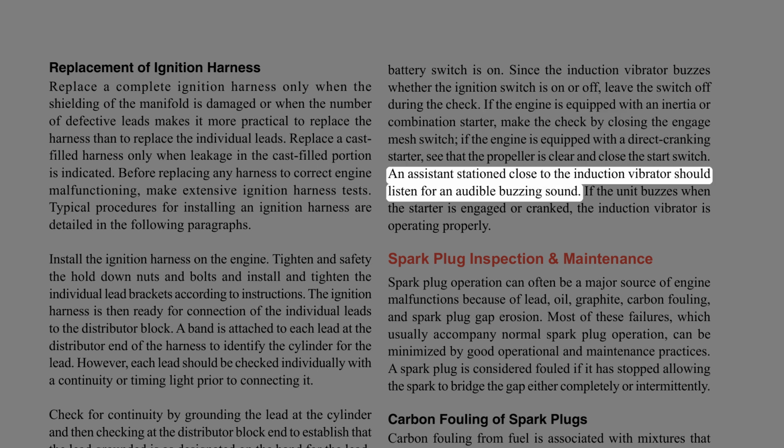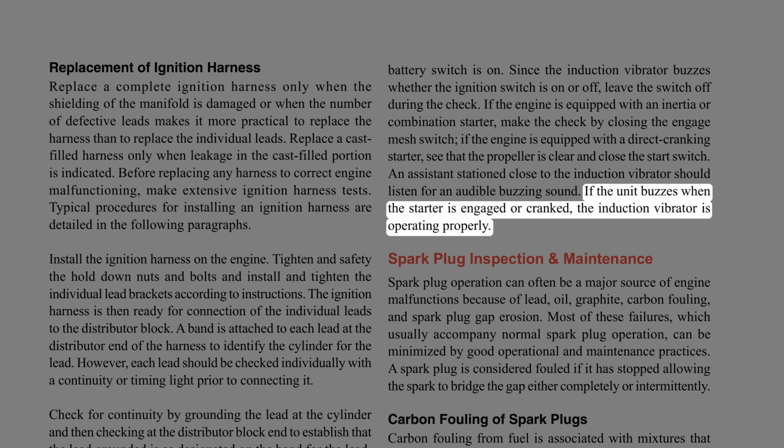An assistant stationed close to the induction vibrator should listen for an audible buzzing sound. If the unit buzzes when the starter is engaged or cranked, the induction vibrator is operating properly.